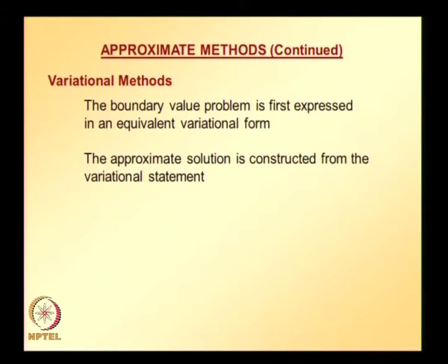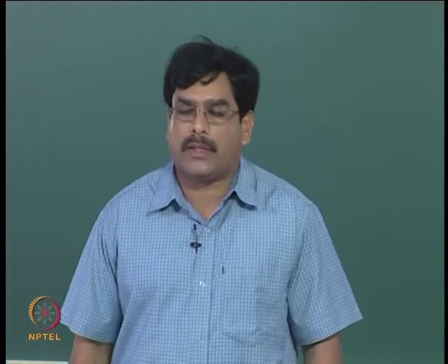The so called energy methods of structural mechanics are based on developing a functional, that is the potential energy functional, and here without starting with the governing differential equation, we directly use some methods to get the equivalent variational functional or potential energy functional first, and the governing differential equations can then be obtained by imposing the necessary conditions for the functional to be minimum.